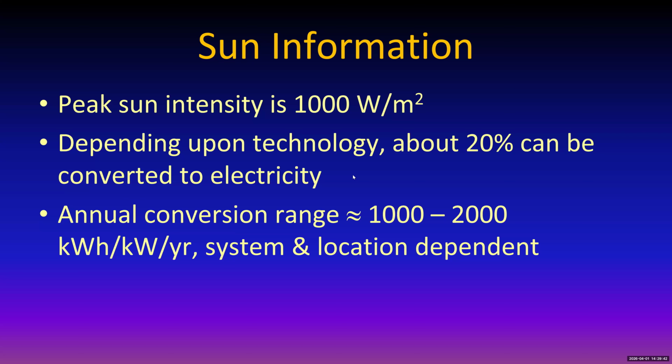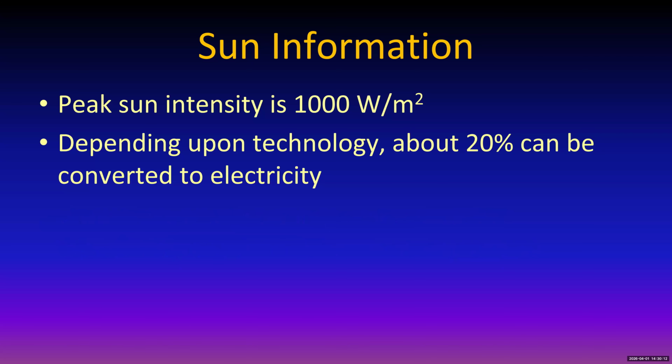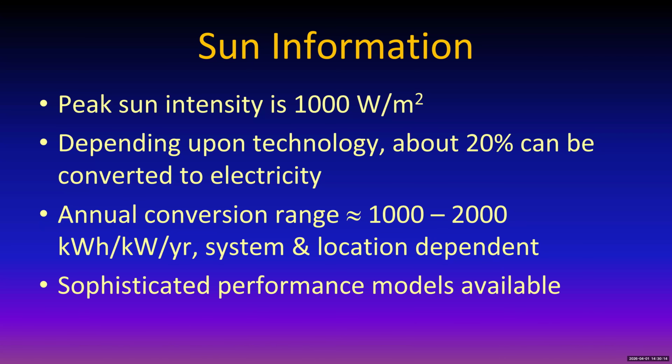Let's say you're going to have a system that's tilted at 25 degrees facing southwest, and you're in Albany, New York. You can then put that information into the computer program, and by the time you blink your eyes, it analyzes on an 8,760 hour per year basis how much electricity it's going to make. And surprisingly enough, it tells you it's not going to make anything at night. Okay, so, and these are those models I've been telling you about.